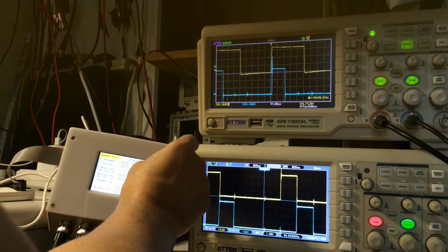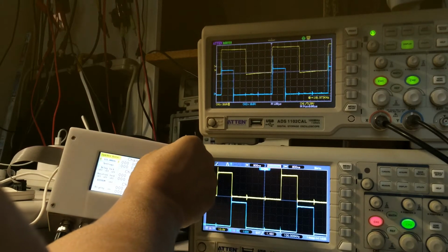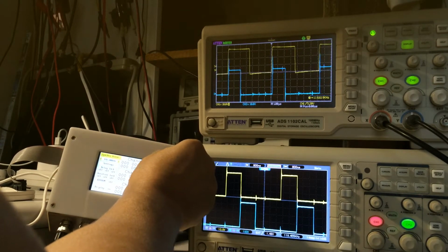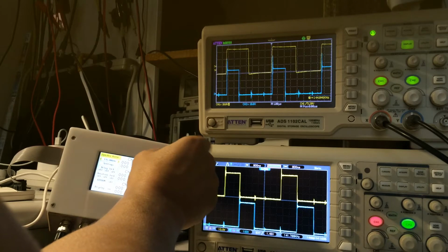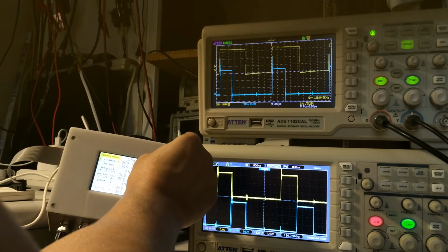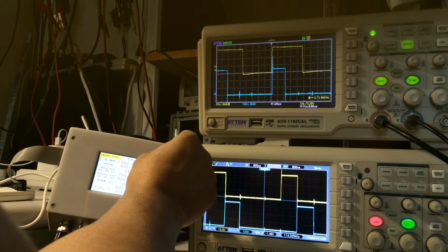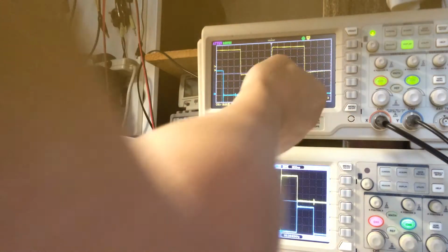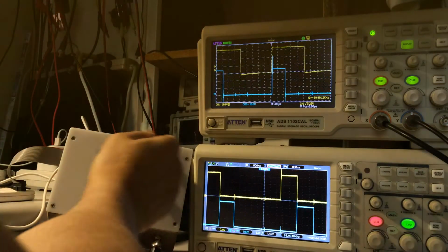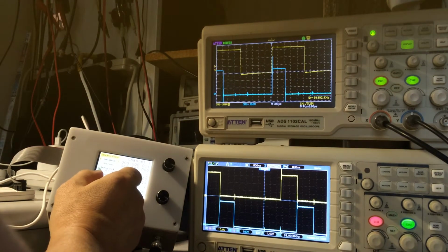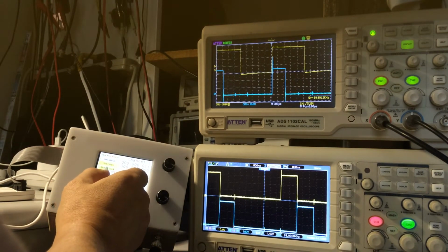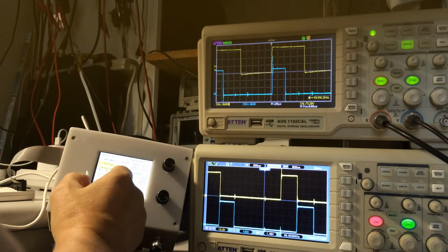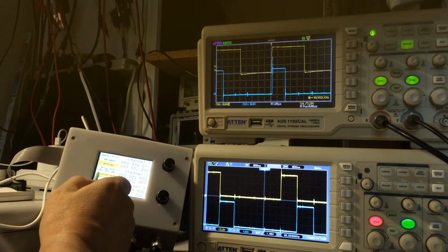Now a link is off. Now we're changing the frequency of the synchro generator, DDS. So you see, we change the frequency, but all pulses stand in absolute position. Sometimes you need it, but sometimes not, because in this situation the relative position between output pulses and synchro pulse will be changed, because the synchro pulse changes, but the output signal does not.